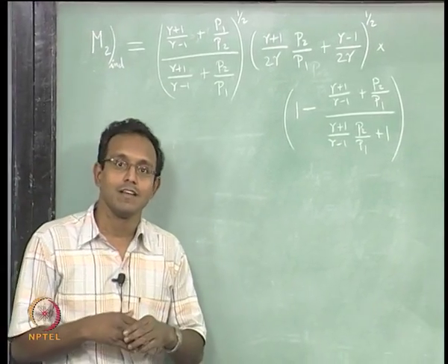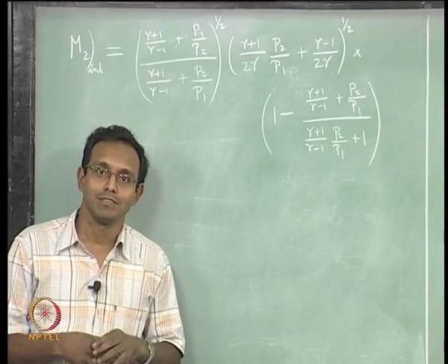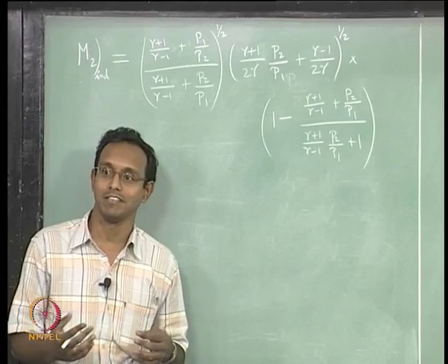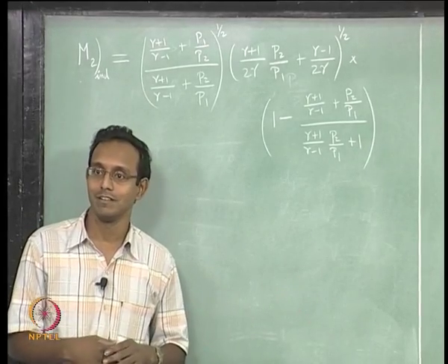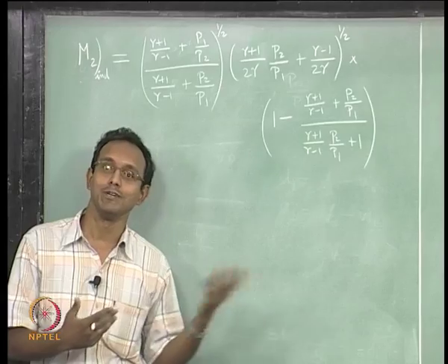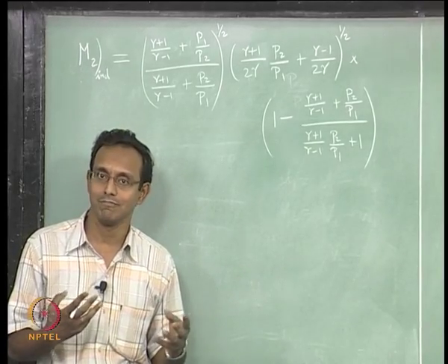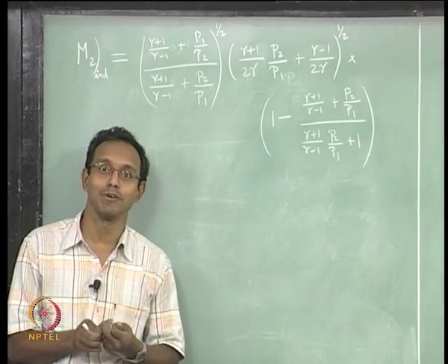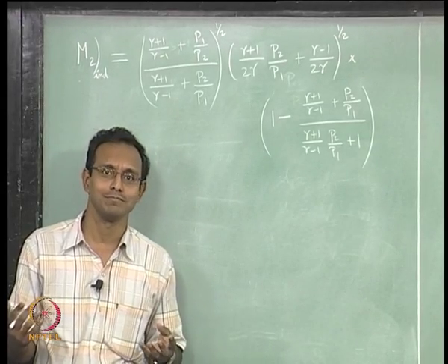And we saw that if it is a very strong, infinitely strong shock, then it is going to induce some finite Mach number finally, which is supersonic, we saw. For gamma equal to 1.4, it was 1.89.